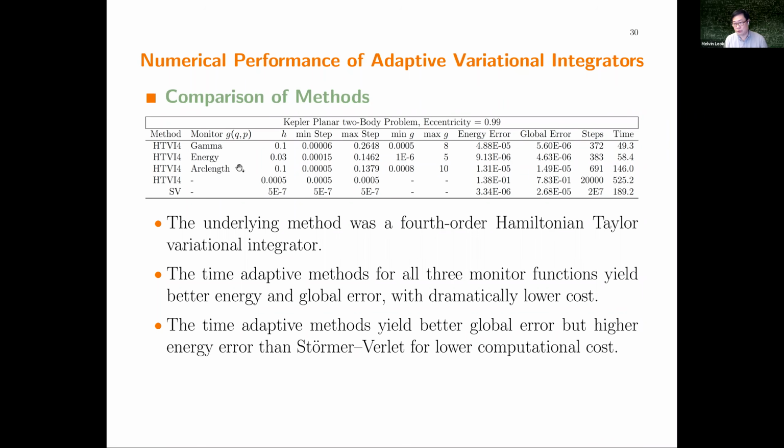So that's something which you prescribe, right? So that's a design parameter in the algorithm, okay? And it's, again, fairly standard. It's like to do things like equipartition of error, right? So if you were to do this in the context of a moving mesh finite element method, then you might want to move the cell boundaries so that the residual error is uniformly distributed across cells, right?